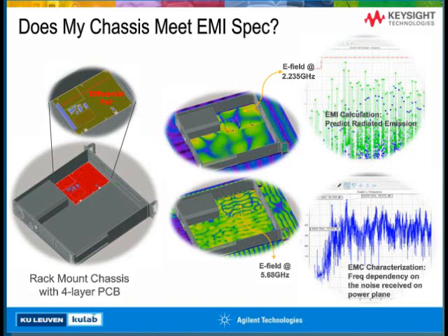The example board is basically a 4-layer PCB structure. And on top of the PCB, we put a test differential pair, and the ground plane is slotted under this differential pair to see how much emission is produced based on the slot on the ground plane.